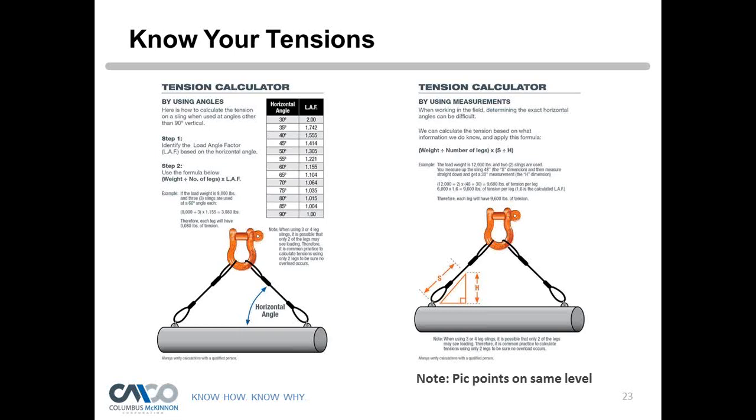So now you know, do I have the right equipment placed? You can see how important it is to sit down and figure out your center of gravity and your share loads, and have an idea. A lot of people may be doing this practice, and they know the weight of the load but they're not sure of their center of gravity, so that's why they use the hoist, and they do it.